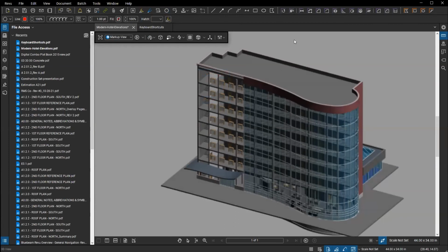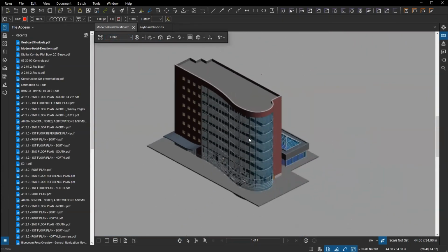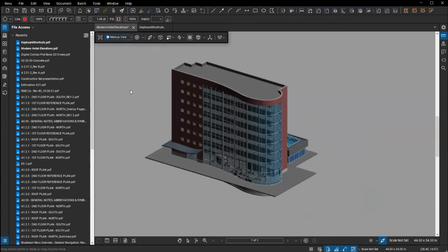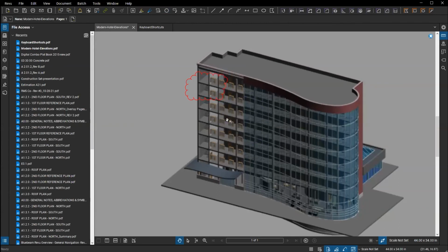So what shows up now is a markup view here, which shows the markup. I can go back to my default view and rotate and spin and move it around as I need to. But I can always get back to that markup view to see my markup at that stage. You can see that content being displayed up there. I've got my markup indicators turned off, but you can grab those to go right back into that too. You might have these little spheres that are popping around on the 3D PDF, however you have the orientation set up as you apply your markups. You can just grab those spheres to jump into that markup view.